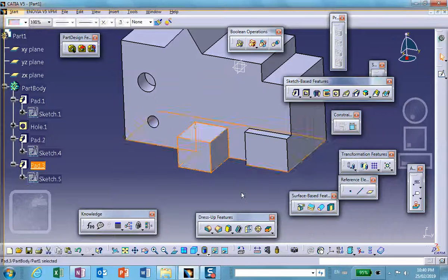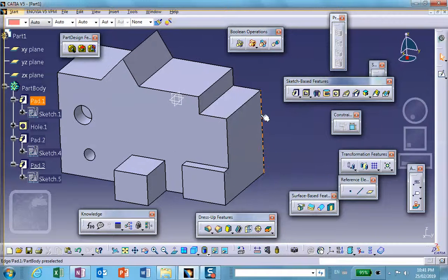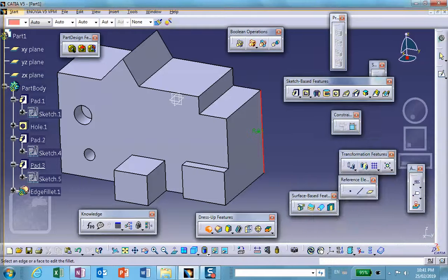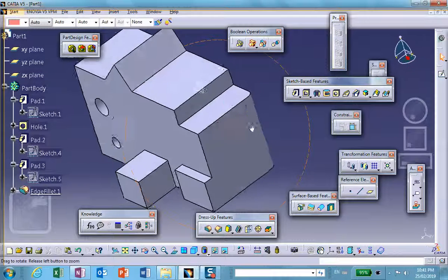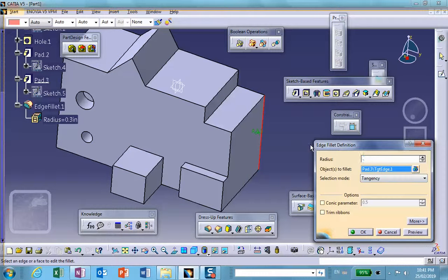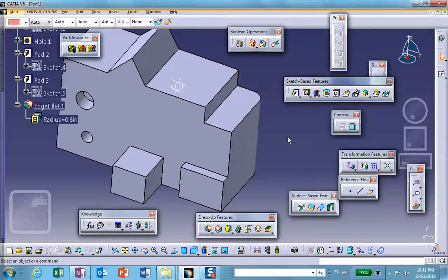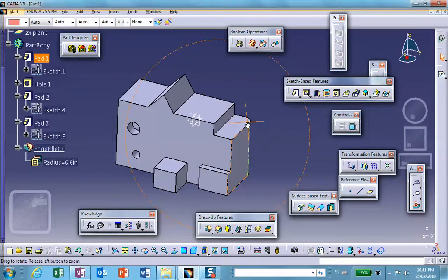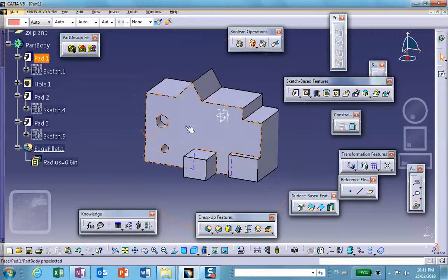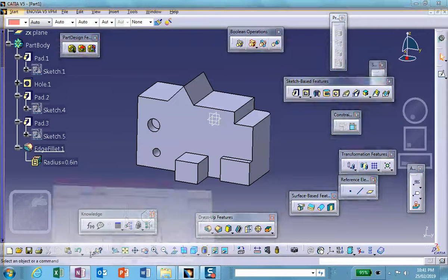Okay, I also need a fillet right there. So an edge fillet over there. And I'll make the radius maybe 0.3, so it looks like there. Okay, actually let me make that edge fillet a little bit fatter. 4.6. Alright, good. So first of all, I'm going to save all of this. Remember, this hole goes all the way through. And I'm going to save this. Notice that it does look like that. Okay.